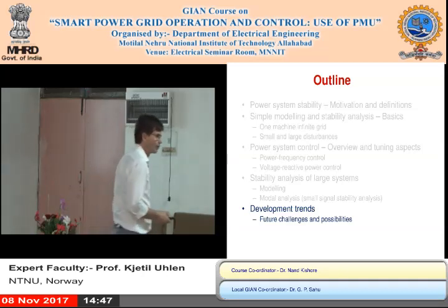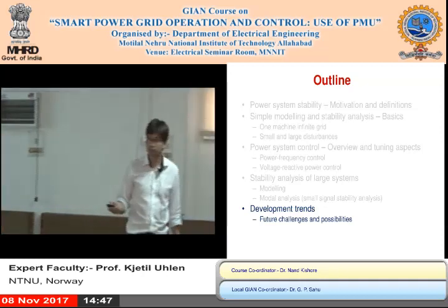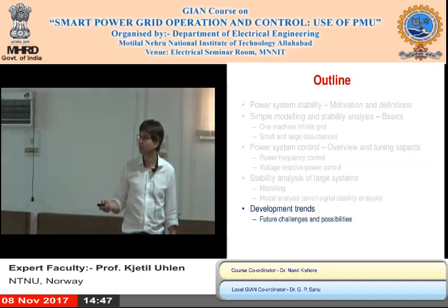In the previous slides, you have seen previously that the local mode was in the range of 0.5 to 1 hertz. Generally, the inter-area mode is between 0.1 and 1 hertz, and 1 to 3 hertz is the local mode. Good question. You talked about this one.